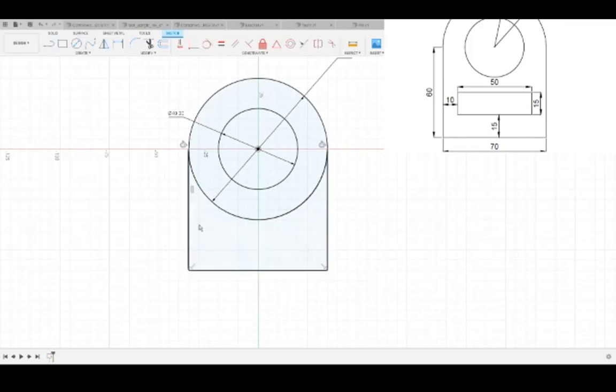So now we have these guys defined, and we have these little symbols here that are defining different things of the shape. Now, some of you who may not know may wonder what these little symbols are. And these at the top here are constraints. When you're not setting numerical definition to some of these parts, you could set geometric constraints instead, which can often take the place of what would otherwise be several numerical constraints that could cause a lot of complexity on your end, because now you have 50,000 dimensions as opposed to having 2 dimensions and a tangency constraint.